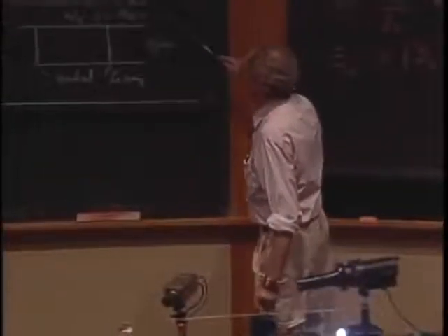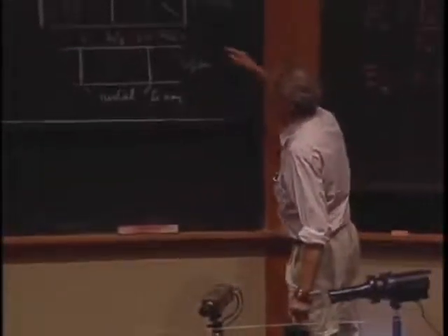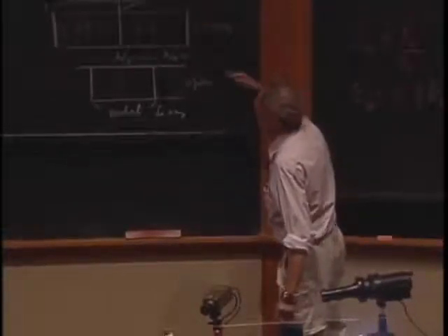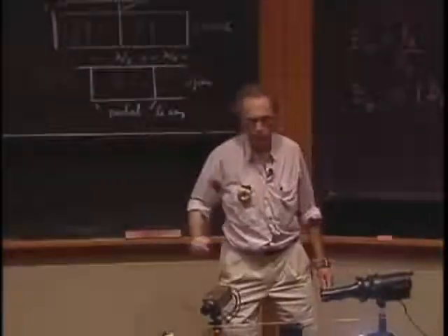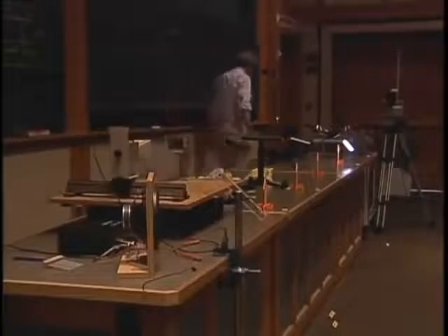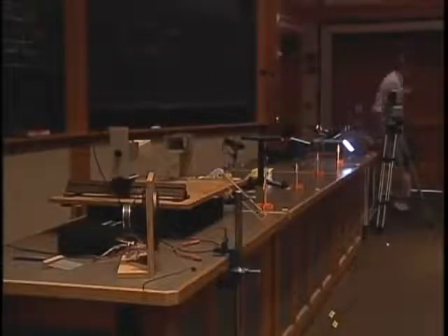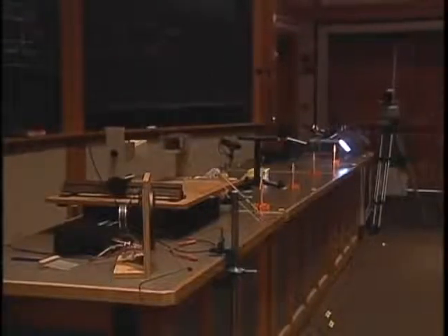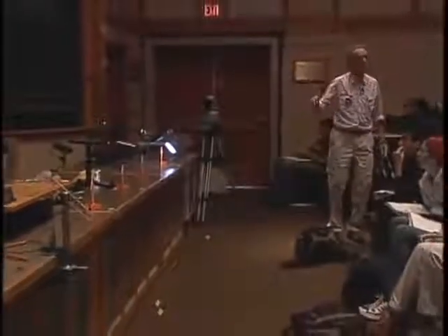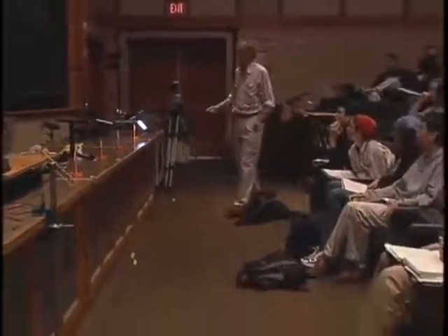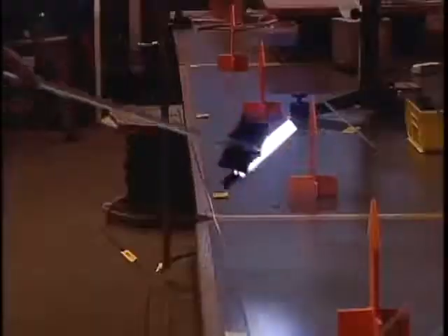But now what I'm going to do, I'm going to short this out here when I put the light bulb right in the middle here. So I'm going to put the light bulb at quarter wavelength. Now when I short it out at the end, I am no longer at resonance. You no longer meet the resonance condition which I meet now at an open end. Something that you can very easily verify.